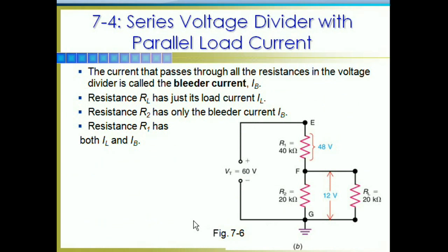All right, so how are we going to design this once again? Well, first I'm going to bring my pen back. I had a little minor malfunction, but we're back to working now. We are going to once again design our voltage divider, first considering the current that's got to flow through the voltage divider portion. And this is known as the bleed current. That's what we have here, the bleeder current.